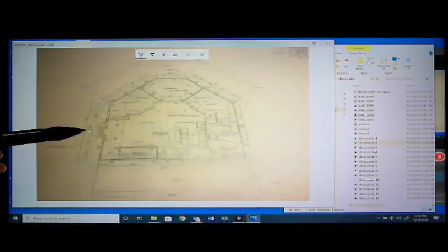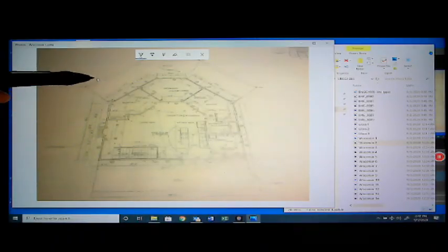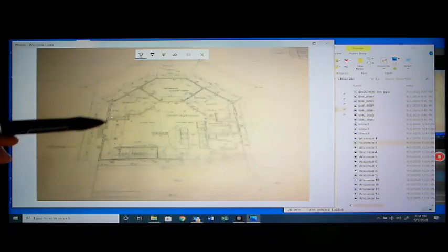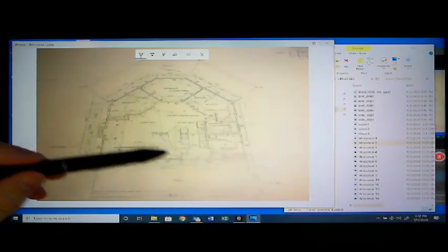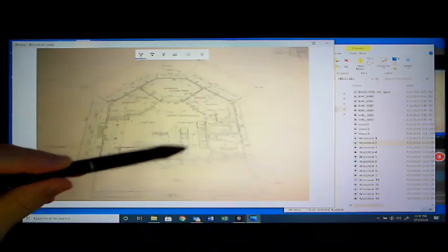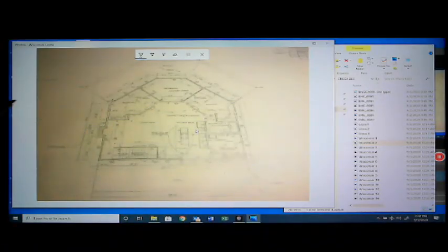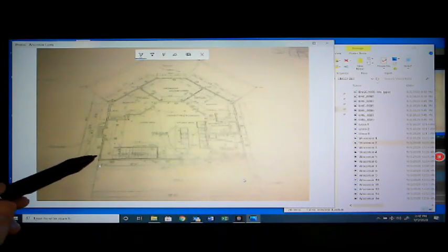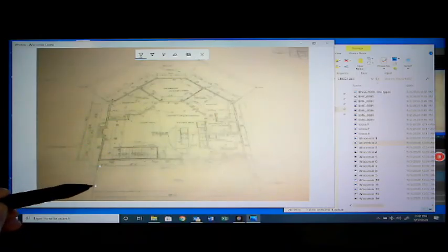Then there's summary dimensions, and then a big dimension here going out to the edge of the greenhouse. You can see there's dimension lines, there's object lines, various symbols. We have dotted lines to show things that are connected. Then out here, this is an auxiliary structure. It's attached to the building, but it's a different construction, so this is done as dotted lines as well. So different kinds of lines communicate different kinds of things.